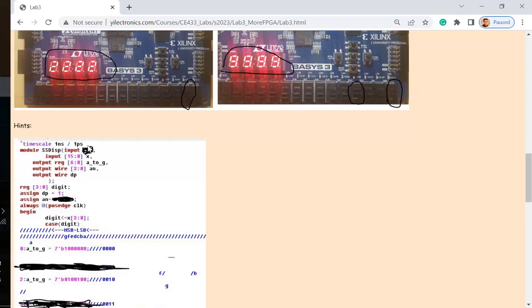However, if you have multiple digits for the display module, you don't want to use 7 times 4, which is 28 pins, just to control every single display. It takes too many pin resources on the microcontroller. To wire 28 wires, just to give a different value there, is ridiculous. That's why they share the same data wires.